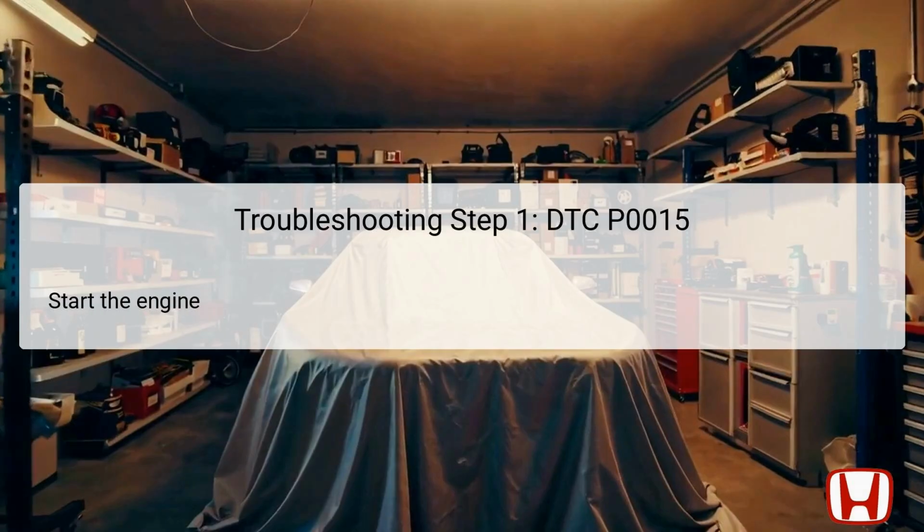attention. The first step in troubleshooting DTC P0015 involves starting the engine to observe its run condition. It's essential to make sure that the engine warms up to normal operating temperature. Ensuring that the vehicle is in a safe and stable location for testing, observe any engine noises and vibrations, and listen for irregular sounds that could indicate ongoing issues related to the timing system.